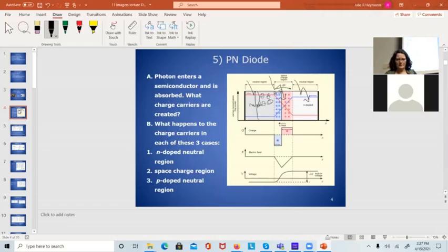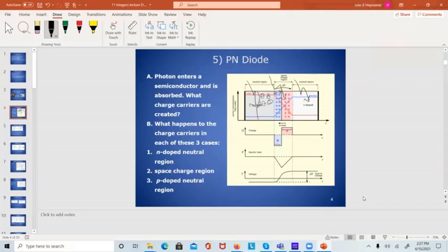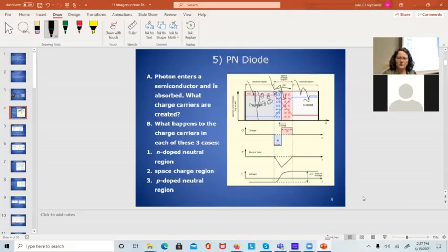Now there's things like quantum efficiency. Quantum efficiency is a measure of how many photons actually hit the diode and actually reduce the charge. Some of them don't. Some of them get absorbed someplace else. So if you're dealing with astronomers, you want the quantum efficiency really high because they get really upset when you lose a photon. And if you're dealing with a commercial application, visible light, you don't worry so much. You want it to be high enough you can create an image, but there'll always be more photons.